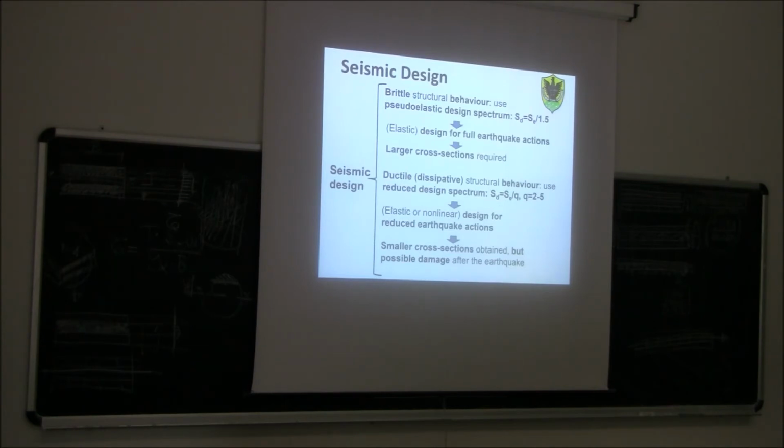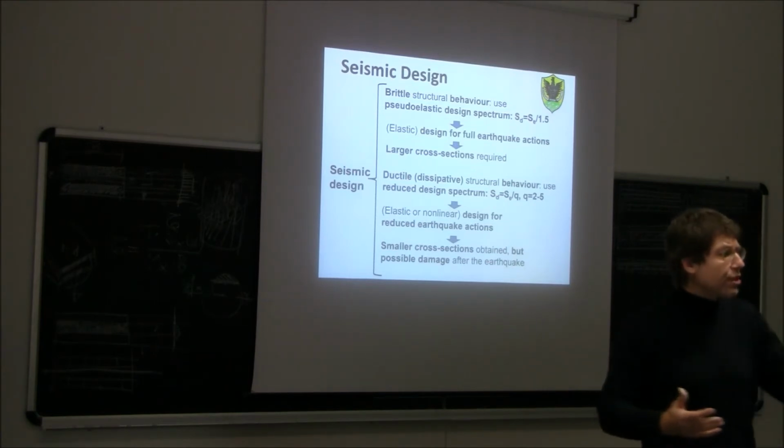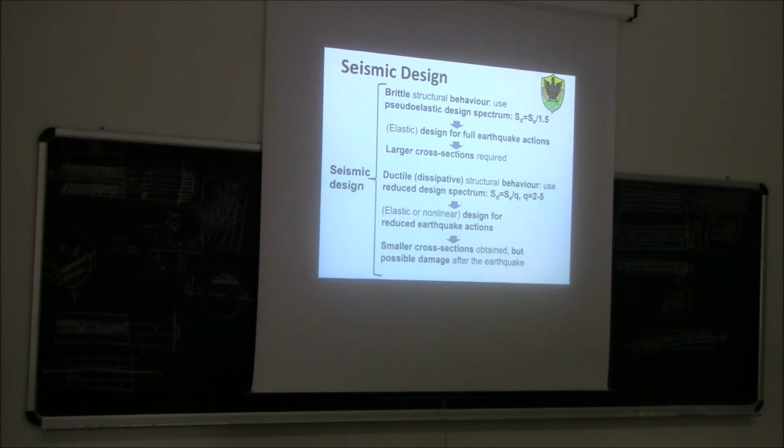It means that you consider only one sixth of the whole elastic seismic forces, and then you need to provide some very important ductility values in some regions. Which region? Well, in your case, you need to make sure that your structure can dissipate energy in order to reduce by a factor of 6. So you had a moment-resisting frame, and the ductility...